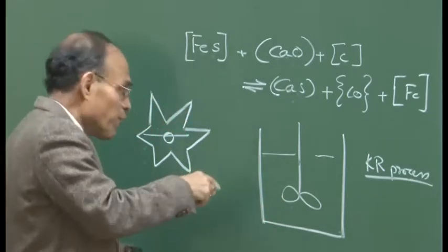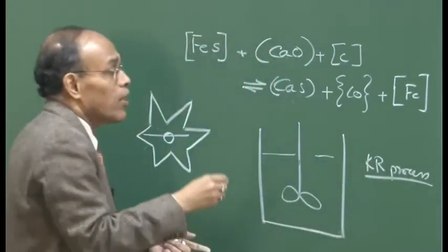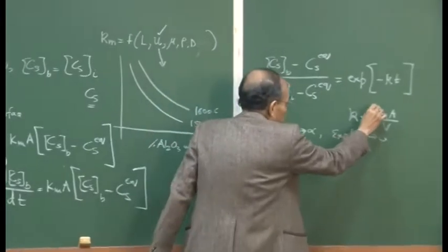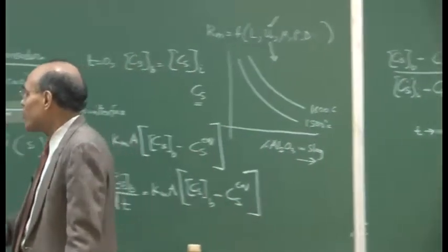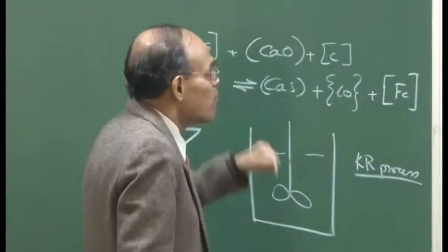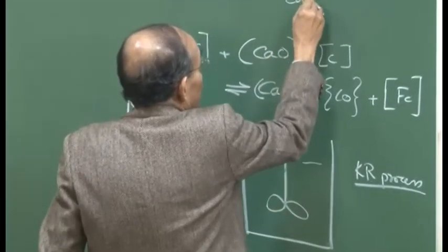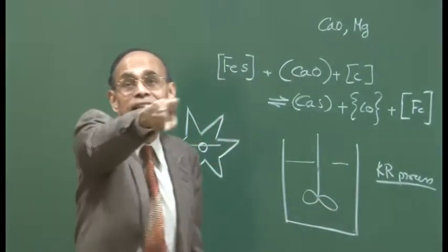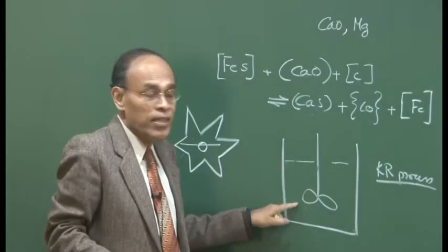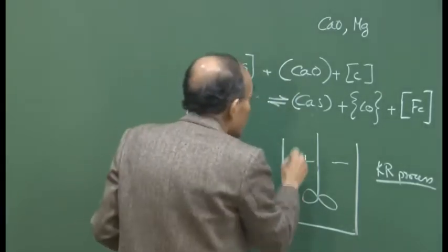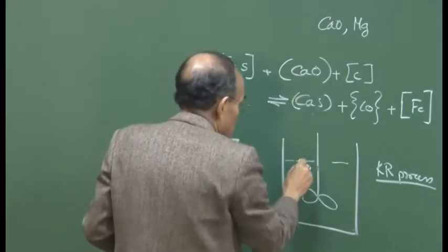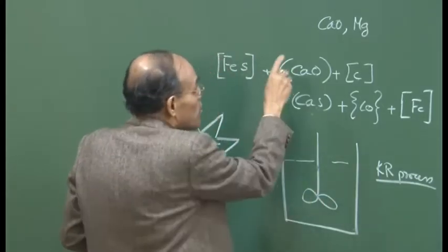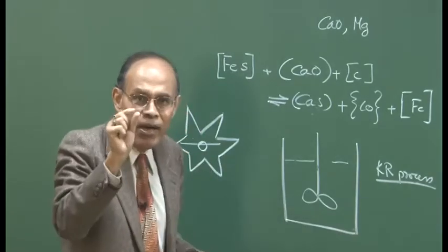So, when you stir it vigorously, we get a very large velocity, and that expedites the mass transfer coefficient. What about the area? Area is also a very important parameter. Now, we are adding various kinds of reagents, as I have indicated: calcium oxide, okay, and solid magnesium powders. So, these are going to be injected into the system. The moment you inject, we have an expeditious dissolution as well as chemical reaction, because of the simple fact that you are injecting in a fine particle shape.